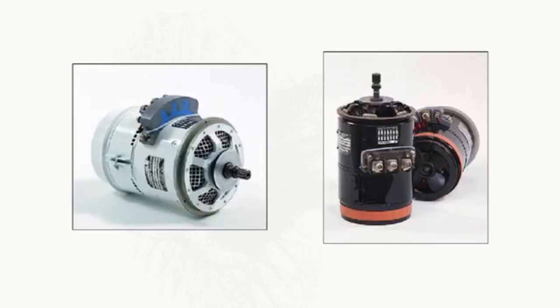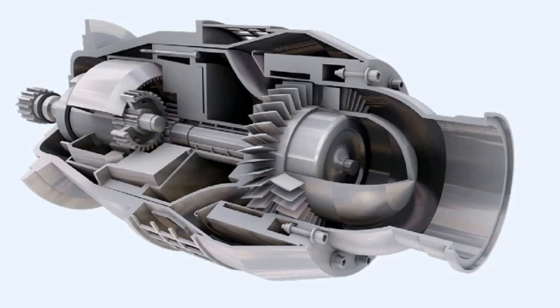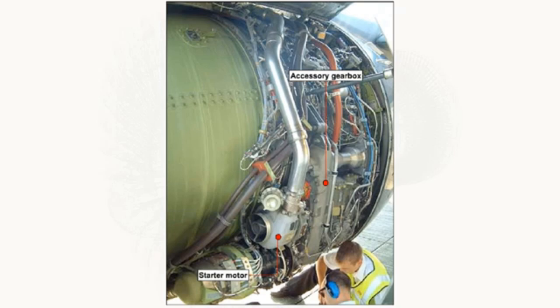Rapidly becoming more popular on smaller engines is the starter-generator combination, which, because of its dual purpose, has a greater usefulness to weight ratio. The air starter motor is possibly the most popular starting system on large gas turbine engines. It's light, simple to use and very economical, insofar as it utilizes low-pressure air as its power source. The air starter motor is attached to the accessory gearbox of the engine.